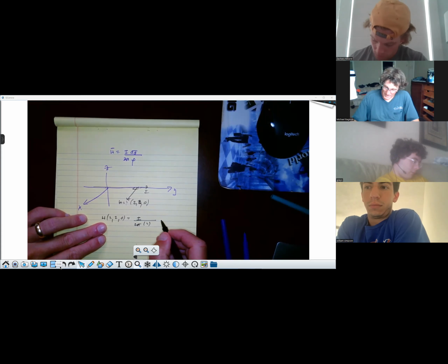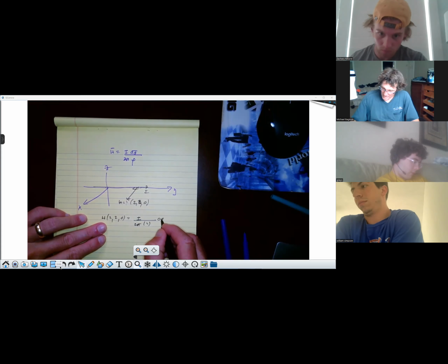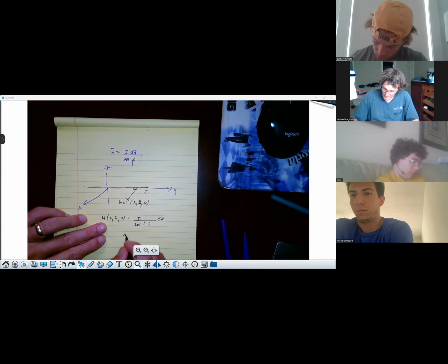Now, my trick is getting A phi, right? So A phi in this one is going to be equal to A I, the unit vector in the direction of current, crossed into the unit vector in the radial direction to the point of observation, A rho.